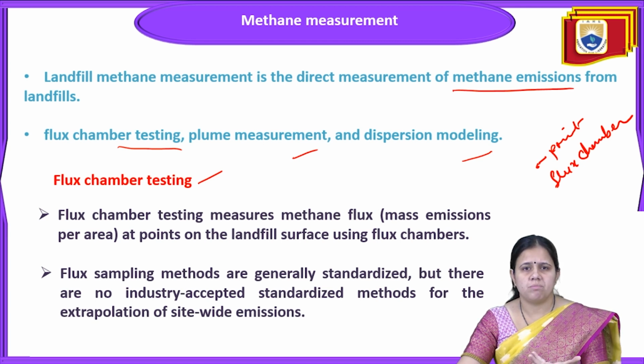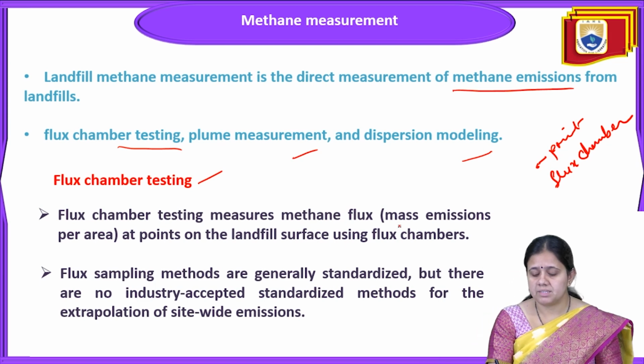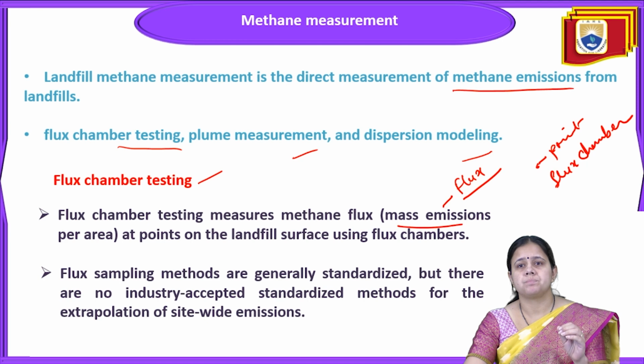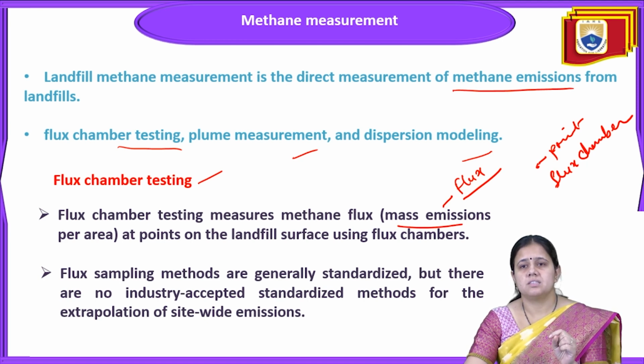Flux means the emission of methane from a point source. You can consider this point source to be a well installed on the surface of the landfill. The flux chamber testing measures the methane flux or methane emission at a point on the landfill surface. The sampling methods are generally standardized, but they are not much industry accepted as standardized methods. But these methods can be useful for sampling methane from the wells at these landfill sites.